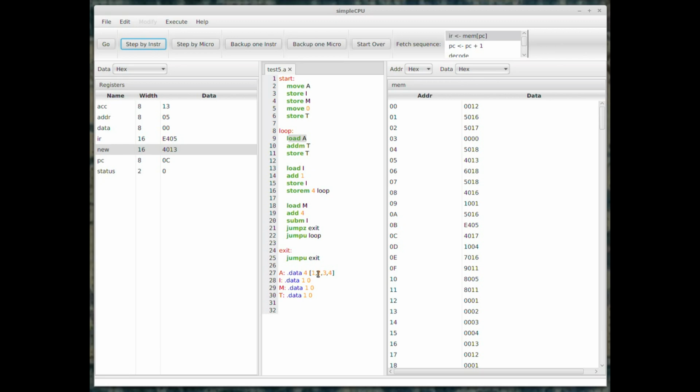We then need to check whether we've read all the elements of our array. So we read in the address of the first element of the array in variable m, which is the value 12. We then add 4 to it to generate the end address, address 16. So that's obviously addresses 12, 13, 14, 15. If I am pointing to address 16, then I've gone outside the array, and obviously I want to stop. To implement that test, I need an if statement. And as we saw in the lab, I would typically do that with a subtract instruction combined with a conditional jump.